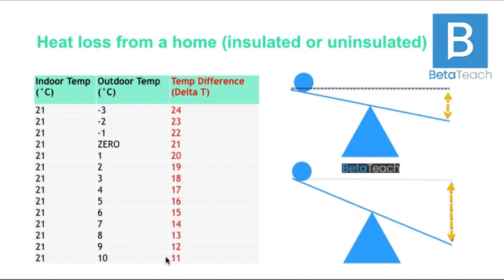Any home can be heated with low temperatures, and we'll talk about that in a minute. And when I say any home, I mean any home. It's because you only have to drive heat into the home to match the speed of heat leaving the home. And in the second video we'll talk about why the condensing boiler got invented. A lot of people think it was invented to capture more heat that ends up going up the flue. That's not why it was invented.